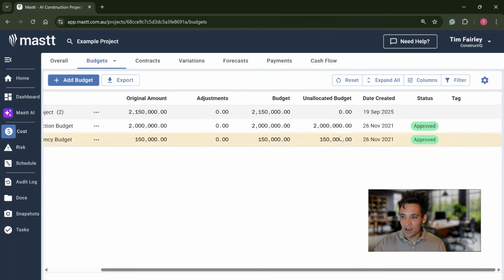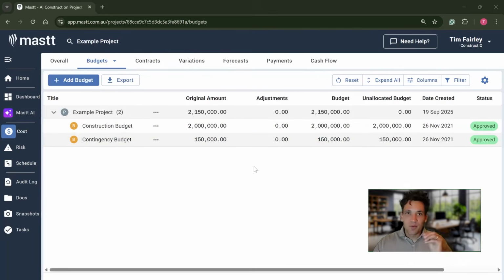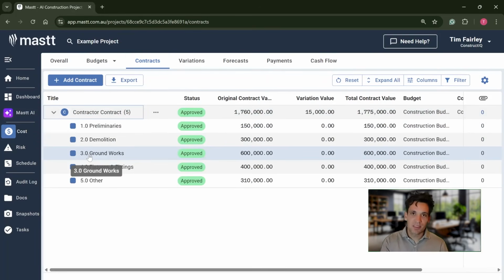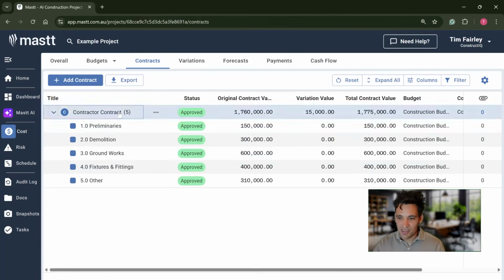Then we have of that budget, there will be allocated expenses and unallocated expenses. So an allocated expense would be when we sign a subcontractor. So we have an earthworks budget, we sign a contract with a subcontractor of a certain value. That value that we've committed to them would be a committed budget. Unallocated budget is where we haven't yet planned exactly what we're going to do with that money. So within our committed funds for budget, we'll have contracts with suppliers, vendors, subcontractors that are going to be doing the work on our behalf. So if we think about it, we have a budget for earthworks. Within that, we have an earthworks subcontractor. If we look at this example, we have a single budget for all the construction works.